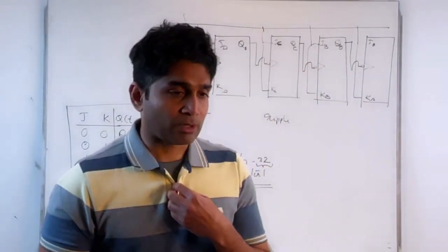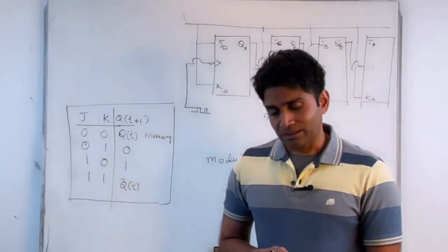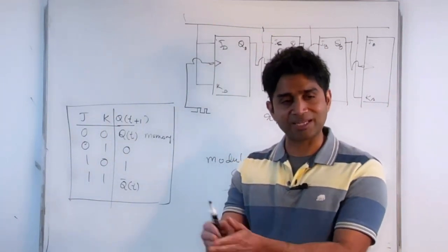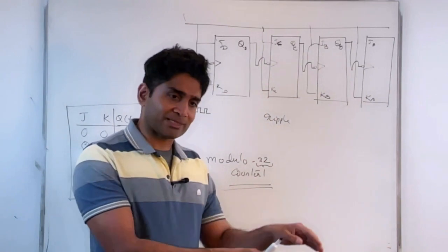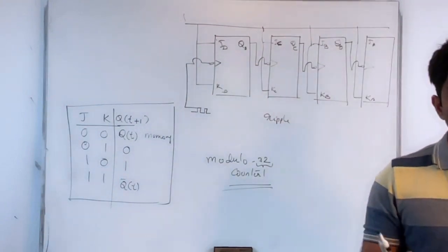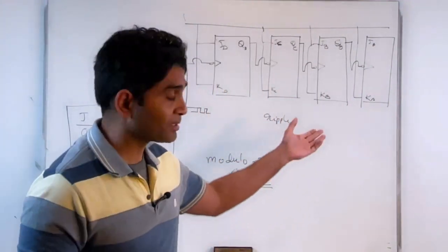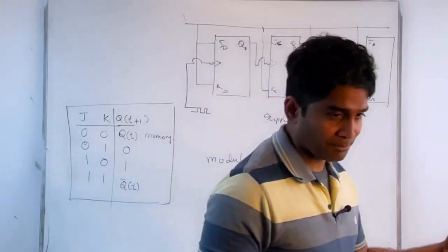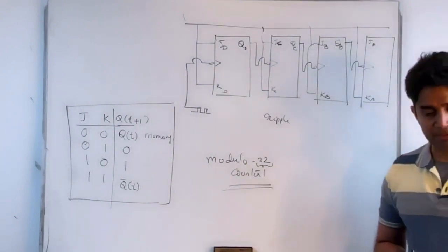Your current clock speeds for your computers are in the gigahertz range, and if I want to show the clock, the time, which shows your hours, your minutes and seconds, I need to really frequency divide that original clock speed so that I can get these periodic signals that correspond to your hours, your seconds and minutes. Right? So if I want to build this using this concept, I need to have multiple flip-flop stages so I can divide this by a large amount. Right? I can frequency divide the original clock period by a large extent.